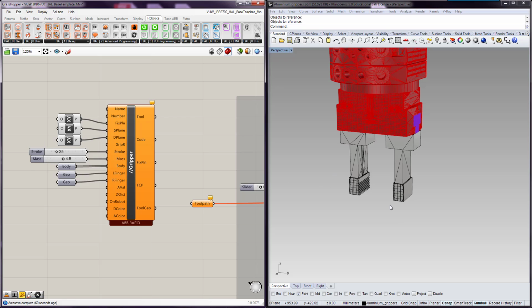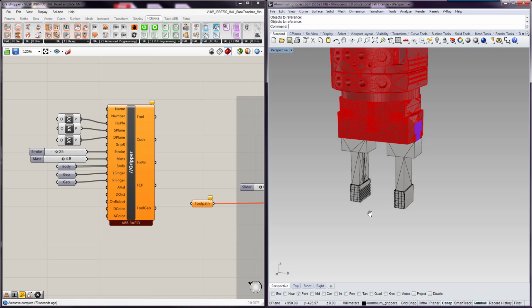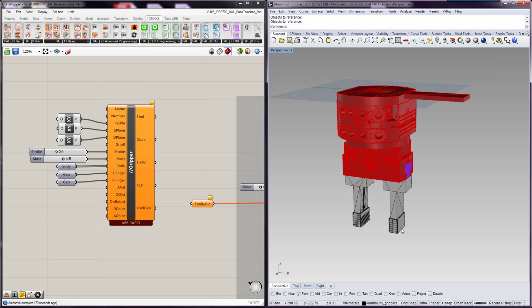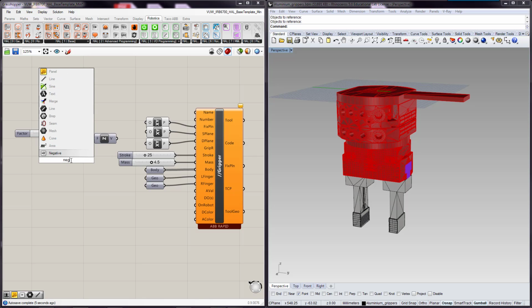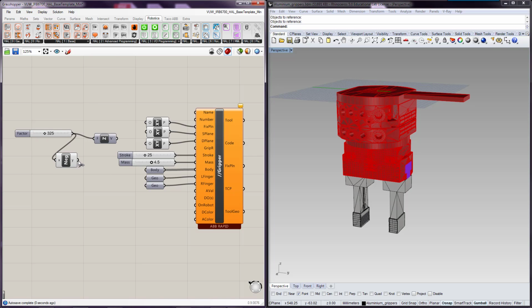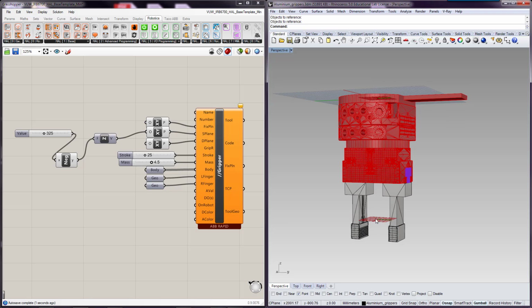And so to set these planes, we could go to the robot and do what's called a TCP, meaning I take this tool and I do a calculation through jogging to figure out how far away the end of that tool is from there. And then that would just be a matter of using a Z vector with a numeric value of whatever that number came out to be, and actually making it a negative value. Right, so I'd feed it through, and that would define the tip or whatever the end of that is.